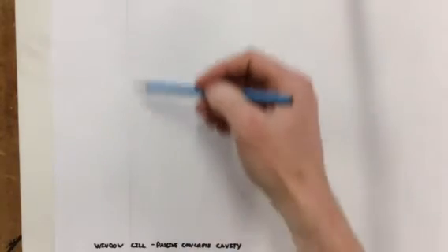We're only going to do a certain part of this now in part 1, and in part 2 we'll look at a little bit more detail on it. We're going to try and get the window sill in, and we're going to try and get our lintels put in at the top as well. That first line, again, I've put in with the ruler.